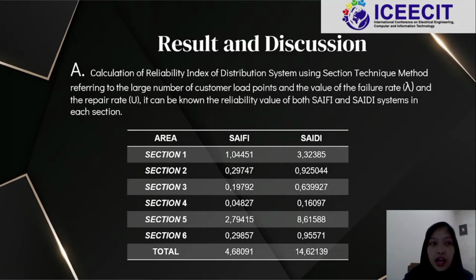And from this table, we know that the total SAIFI is 4.68091 times per customer per year, and the total SAIDI is 14.62139 hours per customer per year.